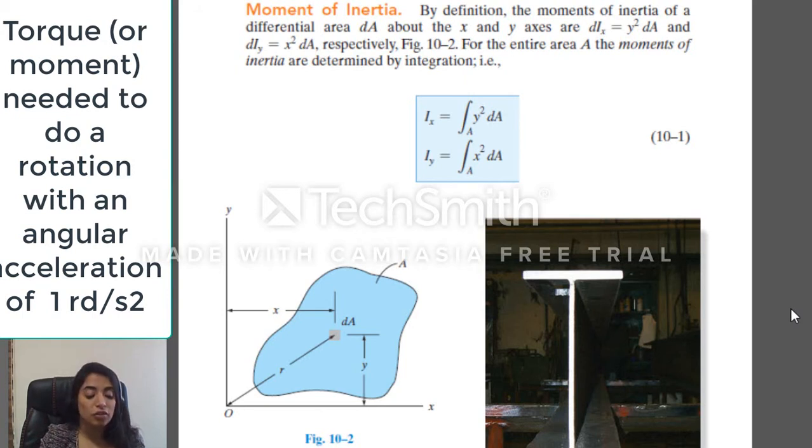So as we said in the previous chapter, if I have the bending moment M, or if I have the shear force V, I can find the stress, and then from the stress I can know if this material can handle this load or not. Basically, guys, the shear force will give me a shear stress, alright? And then I will compare the shear stress with the strength to find out if this material can handle the load or not, while the bending moment is used for normal stress. And then I should compare this normal stress to the strength to find out if this material can handle the load or not.